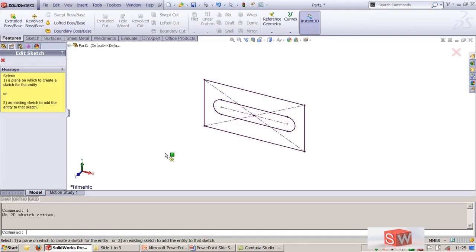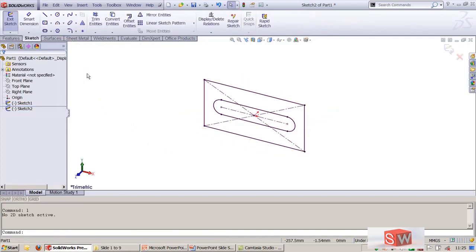Now it will prompt you to select the plane. I'll go and select a plane from this location, select the top, and the command is not activated. What I will do here is press F8, which is used for orienting the plane. Now this will not be customized for this environment since it is in the 2D emulator. Right now